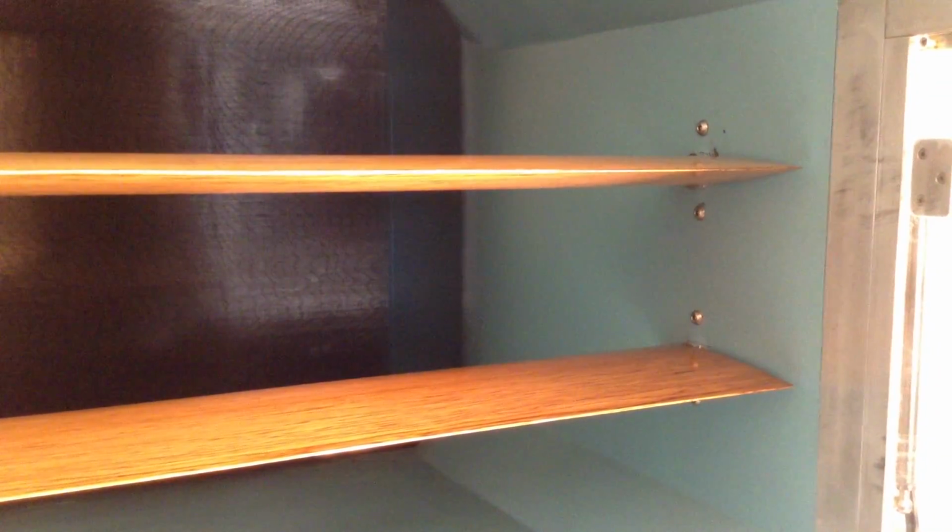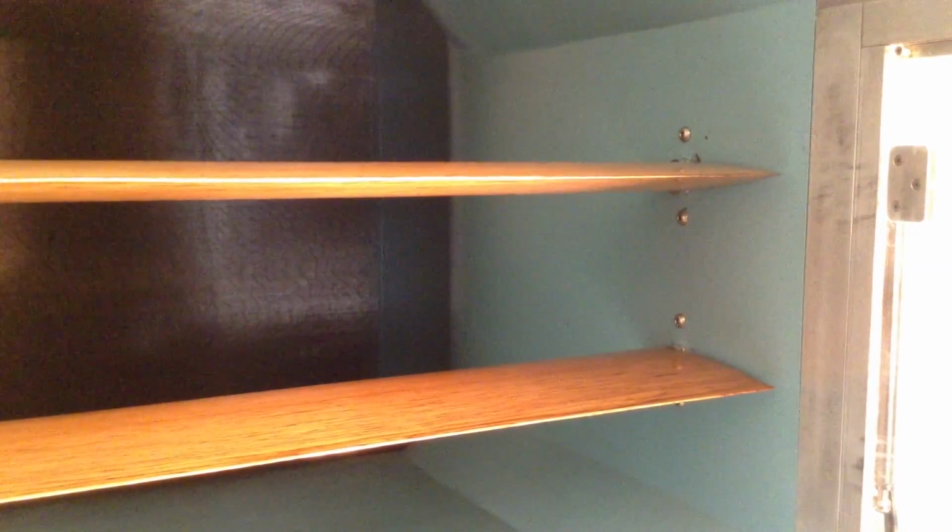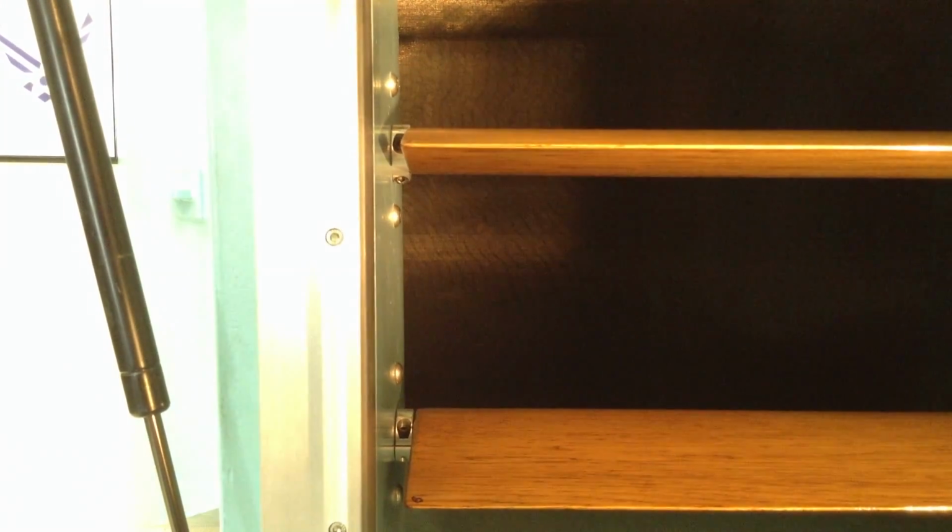Here's a close-up of the gust vanes. The spline shaft runs the full length of each vane. The vanes are a 0015 symmetrical airfoil cross-section made out of FAS hickory that has been CNC'd to the appropriate shape. A metal spar runs the entire length of each vane and provides bending and torsional stiffness during use. As you can see, the ends of each vane terminate inside of the tunnel's boundary layer.